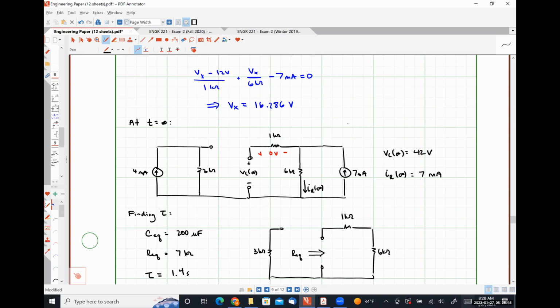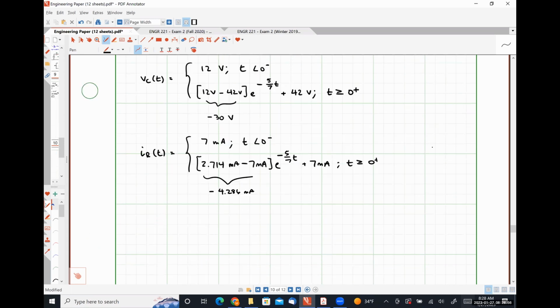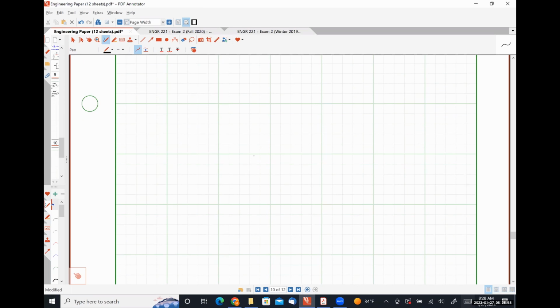Yep, that's exactly right. When that switch changes state, it winds up adding a resistor in, which is going to change your time constant, which is going to change the rate of exponential decay. Graphically, it's going to look something like this, because it has a different rate once that resistor gets switched back in. That's it.